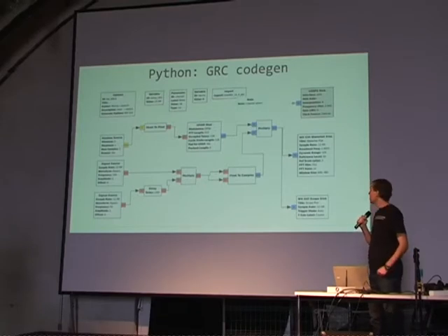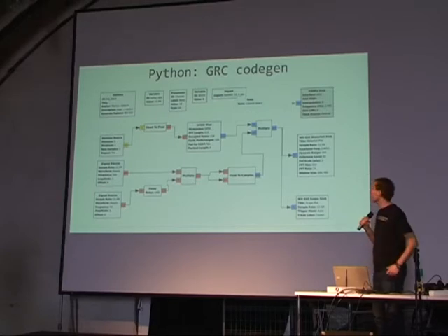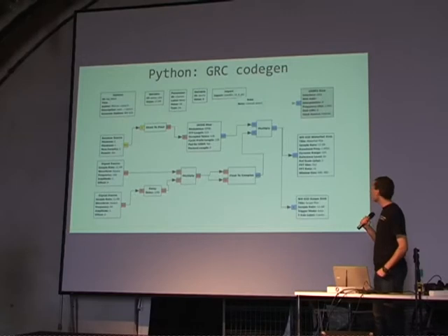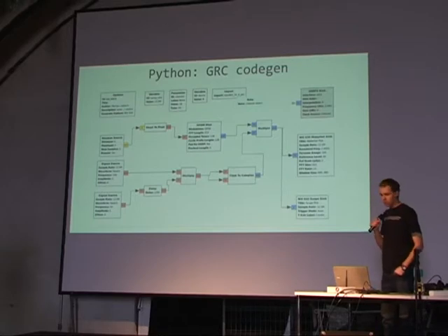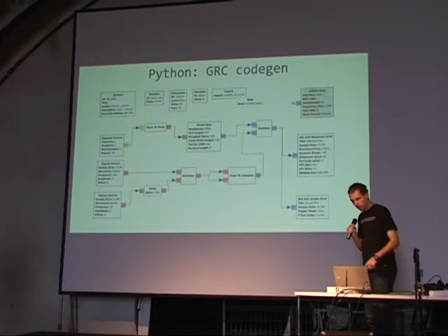You see two signal sources that are used, one with a delay and with a multiplication. This is to pulse the signal so that you don't have a continuous interference, so that the interference occurs regularly and is therefore more effective and not triggering interrupt service routines at your controllers that you're targeting and DOSing them. You want just to simulate interference and not necessarily cause the devices to be irresponsive.